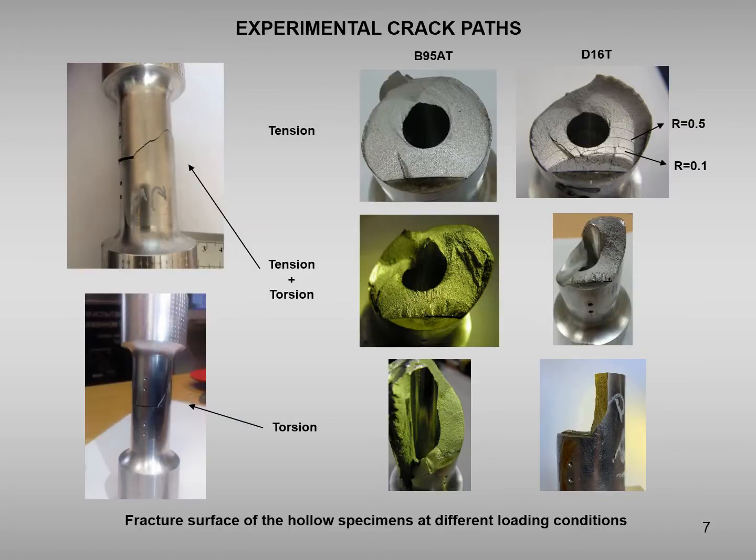The next step of experimental study was crack growth rate tests. The variation of crack growth behavior was studied under cyclic axial tension, pure torsion, and combined tension-torsion fatigue loading with stress ratio 0.1. During each test, the stress ratio was modified from 0.1 to 0.5 for a few cycles in order to create beach marks on the fracture surface.